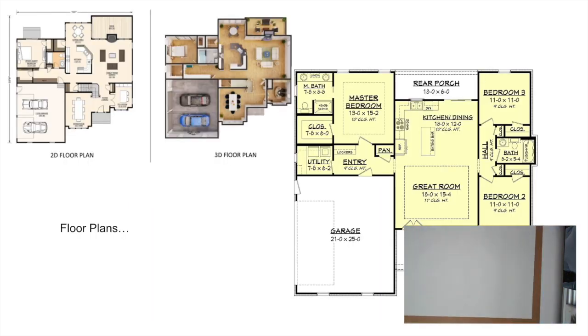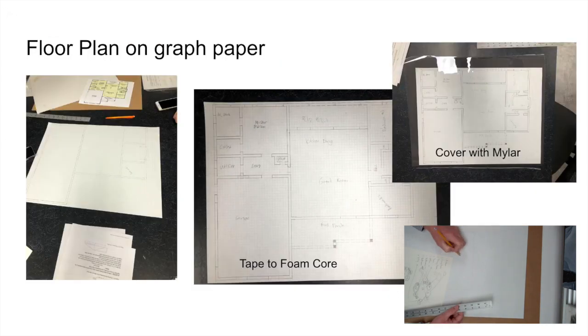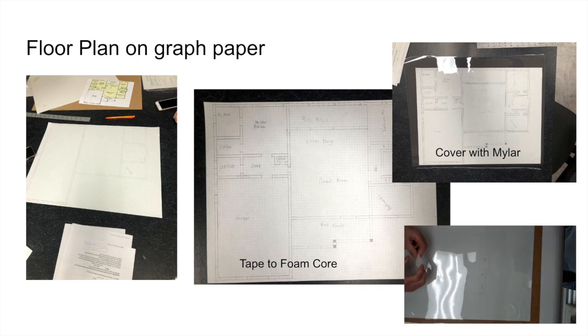Once you have your bubble diagram worked out, it's time to create a floor plan. A floor plan is a bird's eye view of all the different rooms, and we're not worried about the scale of the rooms, just get them general. Sketch your floor plan out in pencil because you probably will make some mistakes and need to go in and adjust. Think about how you maneuver through your home as if you're actually walking through it.